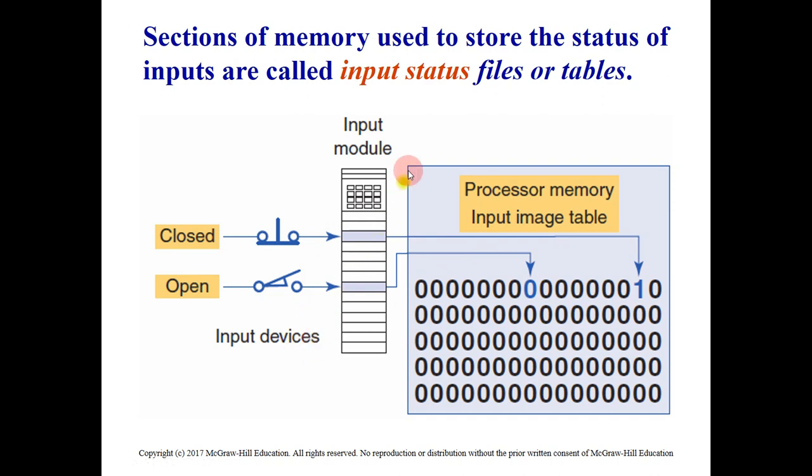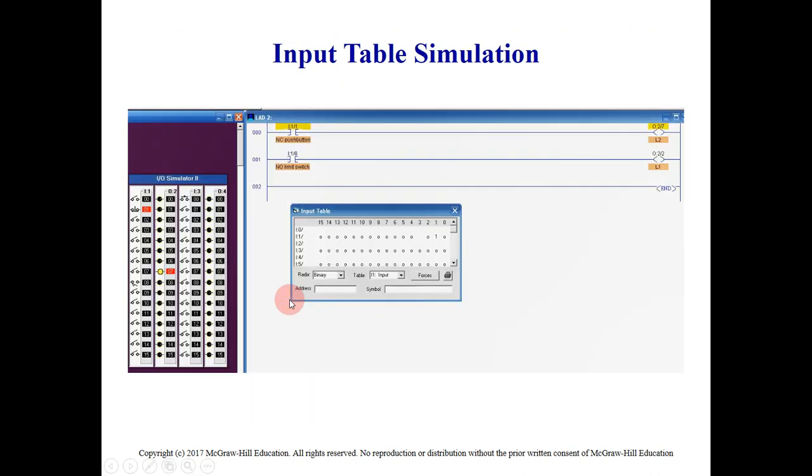So the input status file, or input image table, reflects the status of the device connected to the input module. As you can see here, this is the software we have, the simulator, to simulate the status of this switch. When the switch is off or on, the status of the bit changes.